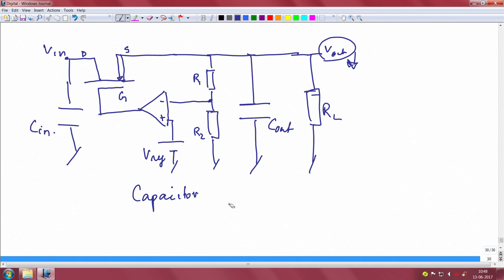So let us move on with this NMOS and CMOS discussion, series pass element discussion. See, an NMOS series pass element requires at times, depending on how this output voltage increases or decreases, a situation where this gate voltage will have to be greater than the output voltage. It actually turns out sometimes like that, which means what would happen?